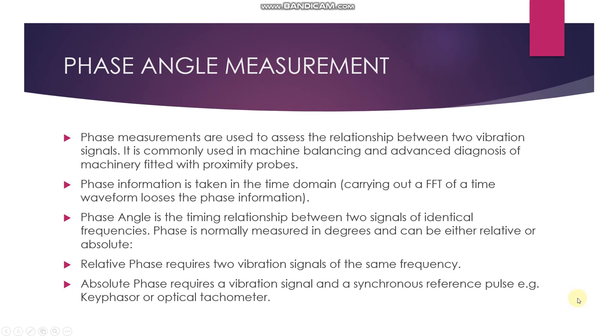My name is Muhammad Izzat bin Mazlan. Phase angle measurement. Phase measurements are used to assess the relationship between two vibration signals. It is commonly used in machine balancing and advanced diagnosis of machinery fitted with proximity probes.